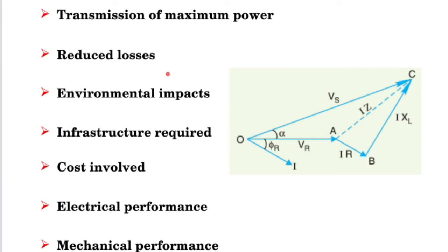And that saline water, moisture, fog, will come onto the transmission line infrastructure. Conductor mainly will get affected. Also, sometimes we might find that there is some pollution if the line is nearer to the highways, like we have highways N3, N2, N4, and N1, and so on. If we run our transmission line corridor along the highways, what happens is that on those highways a lot of high-speed cars travel, and because of that, the carbon particles from the tires of those cars will come and get deposited on the line conductors and insulators as well.